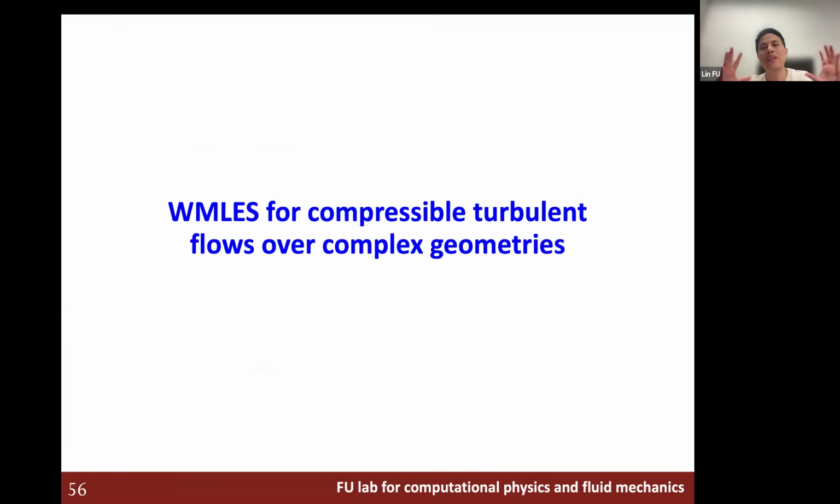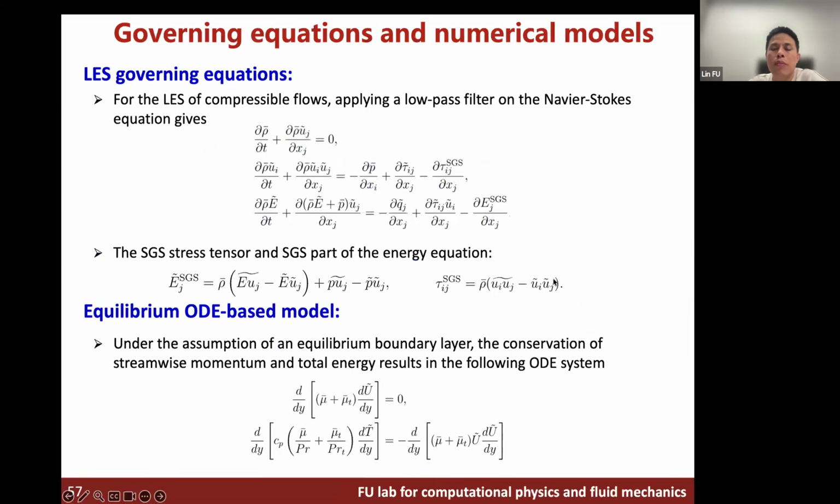So we have so many scaling laws. Just now we mentioned that we can predict the flat plate directly, right? You don't need to solve the governing equations. But how about industrial applications with complex geometry? We can incorporate all the scaling laws into a new wall-layer framework to predict industrial applications.